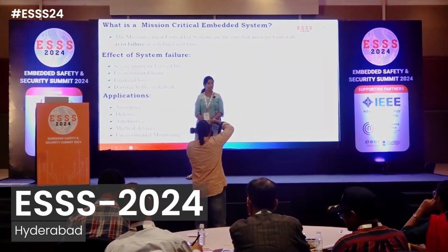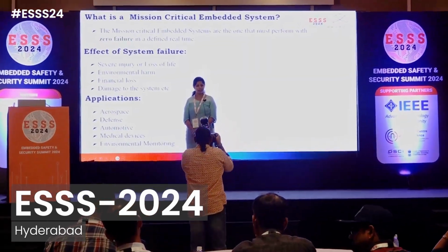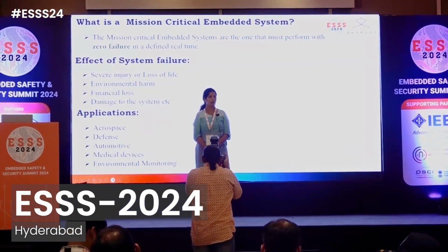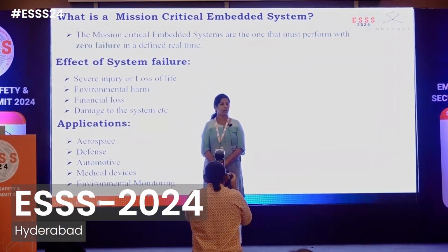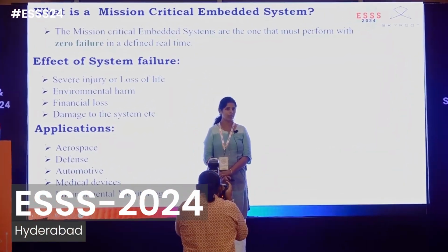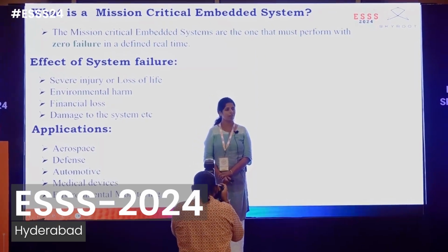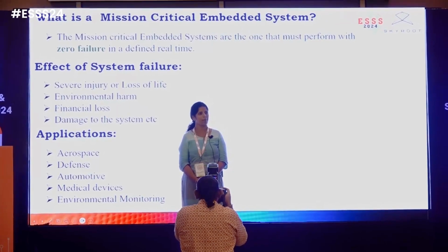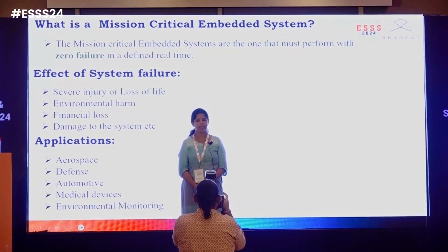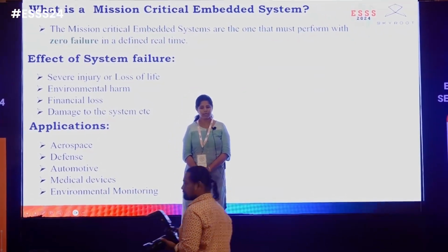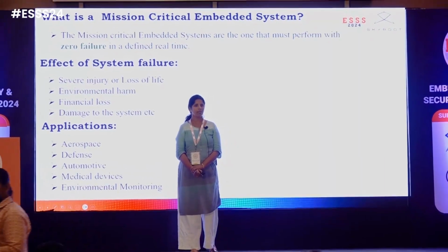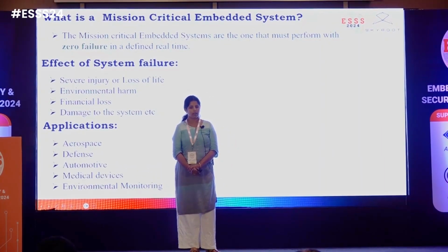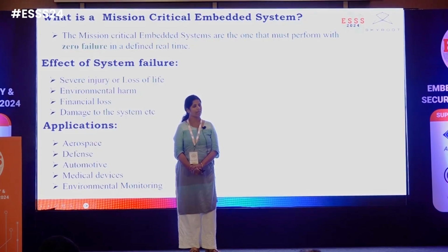So the effect will be catastrophic, such as severe injury or loss of life, or environmental harm, or damage to the system, a lot of resource wastage, or financial loss. Anything which is very hard and difficult to recover back. That is the mission critical embedded system. So the mission critical embedded system is the one which should have zero failure and perform as expected in a very strict real-time requirement.